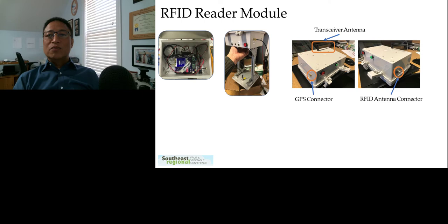An off-the-shelf aluminum extrusion and an enclosure was modified to house the electronics. The power, switch, micro SD socket, transceiver antenna, RFID antenna, and the GPS connector were routed outside the box for easy access. The RFID antenna was attached to the box by aluminum extrusion bars. Space between the bottom of the electronics box and the antenna was chosen to provide clearance for connectors and yet not interfere with landing the SUAS or drone.